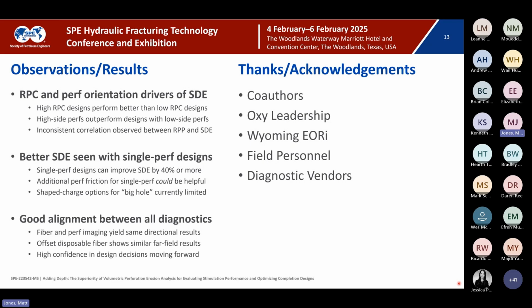One of the issues that I've seen with these types of charges is that they are not as consistent in terms of initial hole size. They tend to have a higher standard deviation compared to standard deep penetrator charges, which is what you would use for multi-perf clusters. So that's one of the drawbacks.